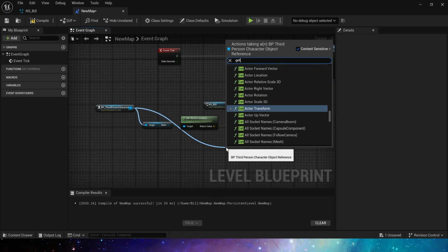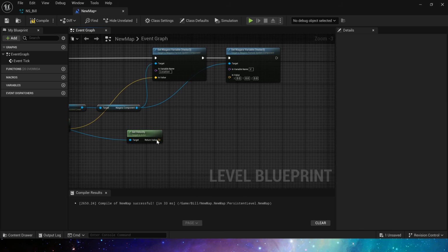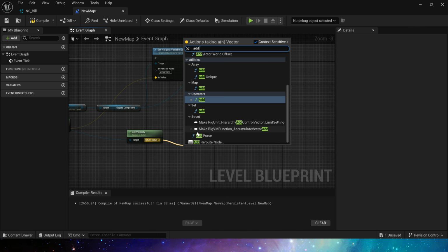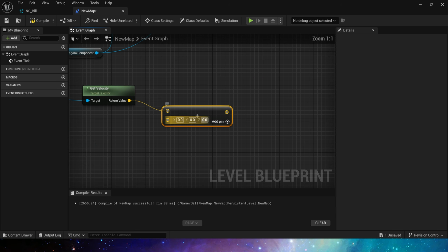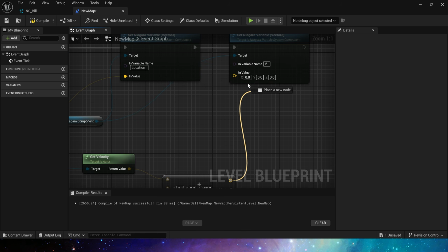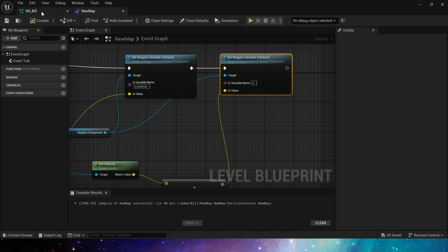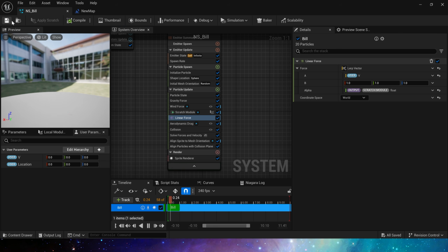then the velocity, we get velocity, add a value in the positive direction of the z-axis, because the character has no velocity on the z-axis when moving, and we want the particles to fly up, so add the velocity of the z-axis, such as 500, and then connect the value of the velocity output to V. That's it. Niagara gets the location and velocity of the character.